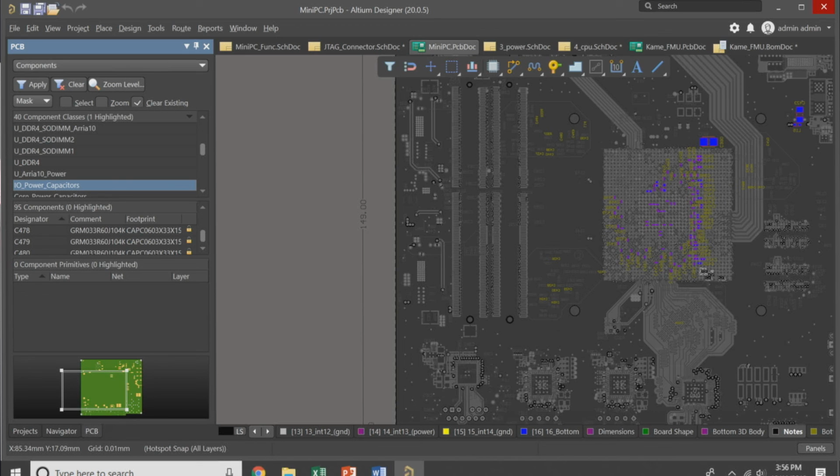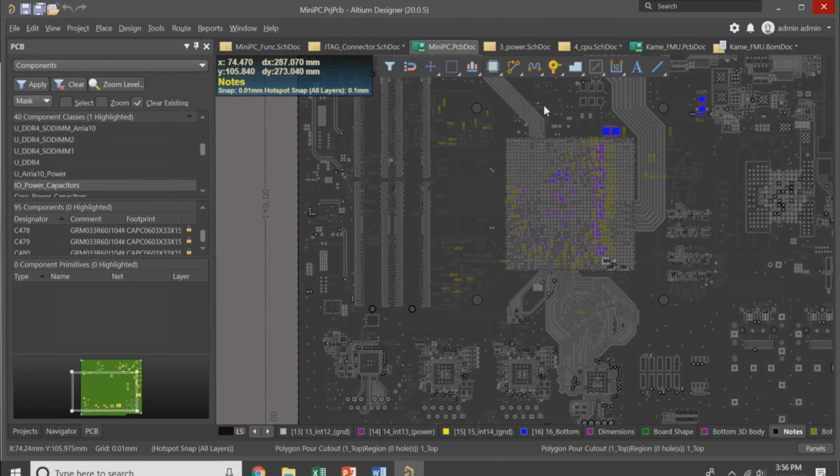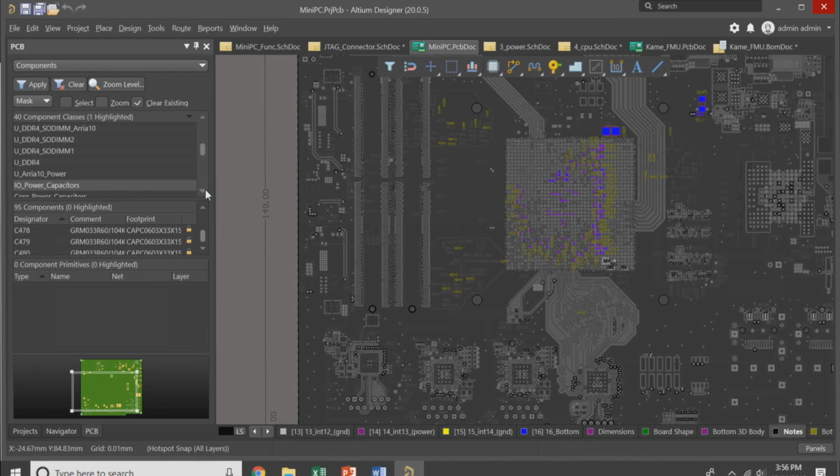You mentioned X signals, and one of the things we found ourselves doing in large Xilinx parts is mapping the delay in the die itself over the total length matching for X signals. I heard a rumor that you were going to address that in one of the next phases of the software. I wonder how far you got with that. I know they've introduced the pin and pin package mapping.